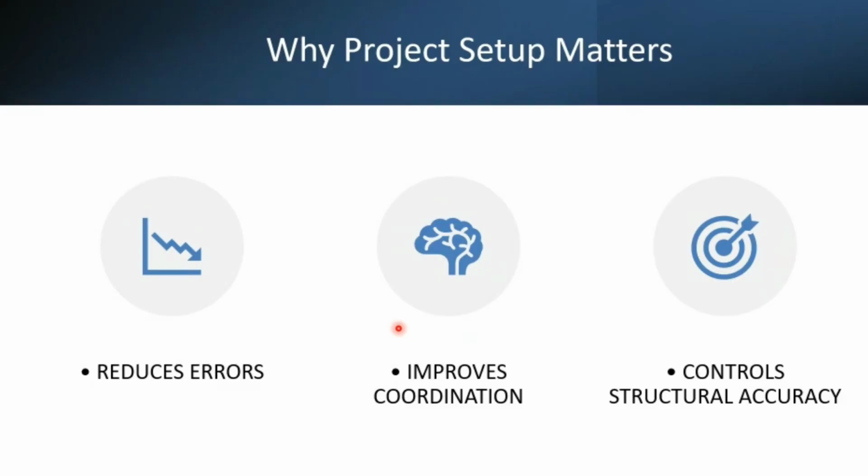If you have accurate levels, grades and coordinates, then you can model your structural elements in real-world coordinates with exact and accurate lengths, dimensions and properties. So you might have a highly accurate structural model, which helps you then analyze and design your model accordingly.